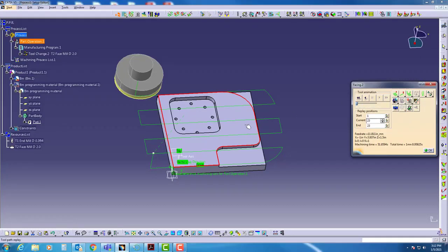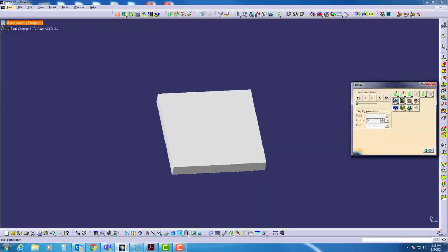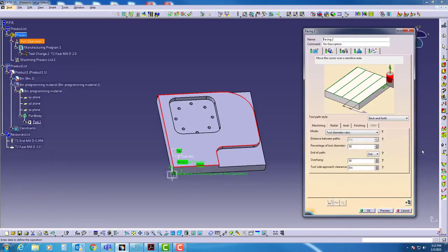So I'm going to simply hit rewind. Now once your toolpath looks good and you want to see it in simulation mode, you can see the video of it, and make sure I always hit the back button. That usually takes you to the top of your program, but we're not running very many tools, so I'm going to hit play. And you'll see that it worked just great. Now remember, we're only taking off 1/1000th of an inch, so that's all we're showing right there. So with that said, I'll hit OK, and then we'll come up here and hit OK as well.